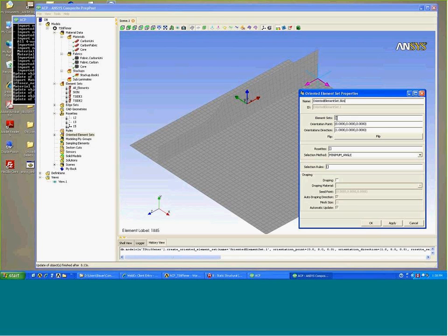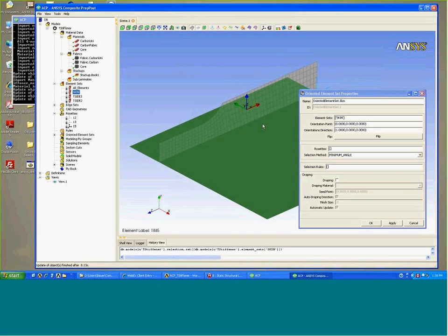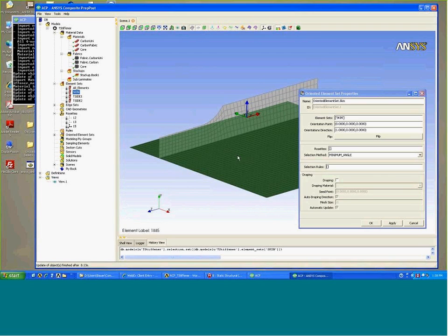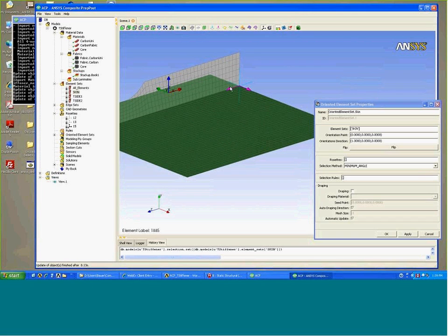What this does is combine element sets, or groups of elements, in this case the skin element, and in this box here we define the normal orientation, essentially the definition from the mold surface or the bottom and the direction normal. So let's define our normal orientation of the skin as extruding downwards. We're going to have a T-section on top of the skin, and the skin extruding downwards. We have an orientation point, shown as a preview in this direction.